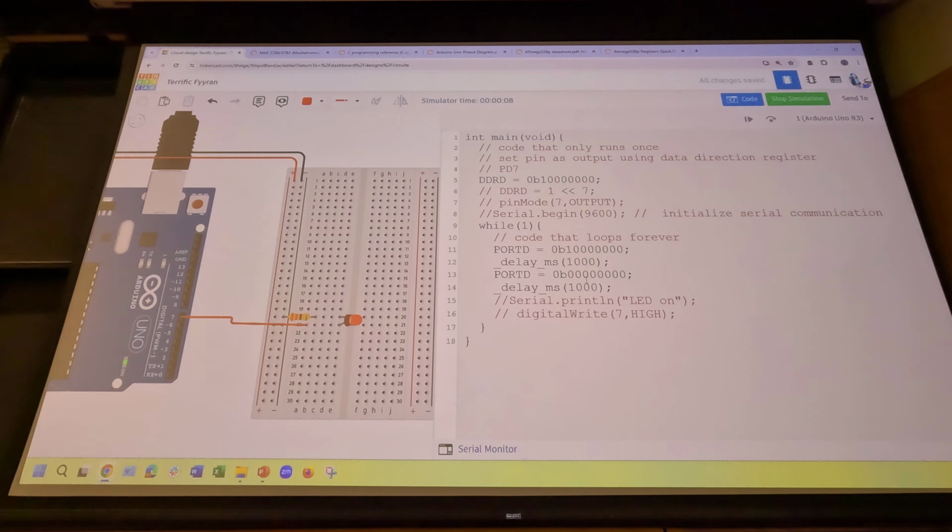Yes? Or do you need an underscore before the delay? Yes, the question was, do you need an underscore before the delay? This command is specific to C. There is a different, but nearly identical Arduino command, just called delay, without the underscores and without the ms, that also just does a delay in milliseconds, so I could do delay(1000).